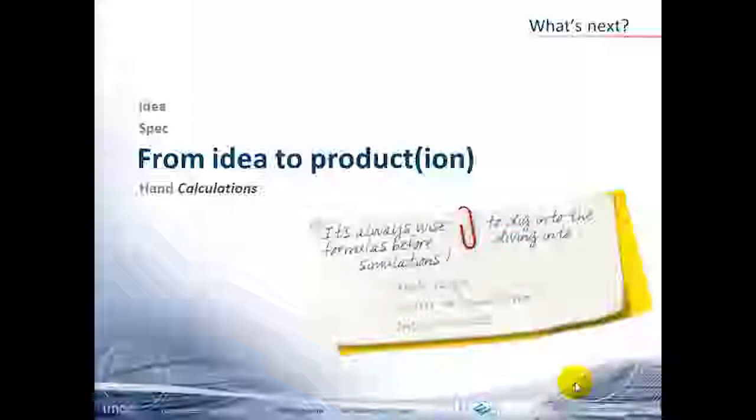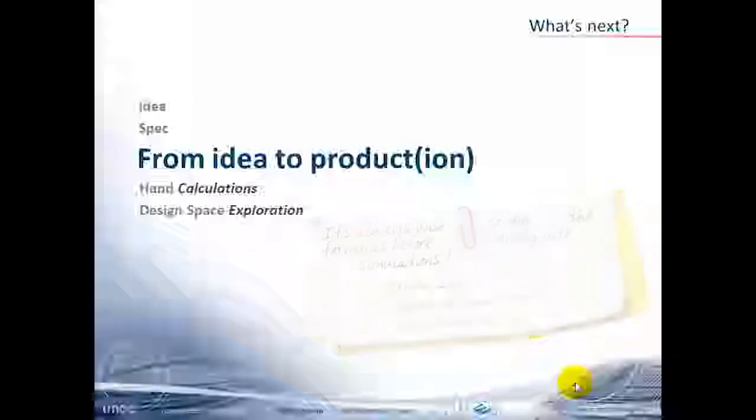some hand calculations before diving into the simulations. And I emphasize this enough. Don't trust the simulation results without having done some calculations before. There are always nice graphs and curves, but you should compare with what you have done in the beginning.